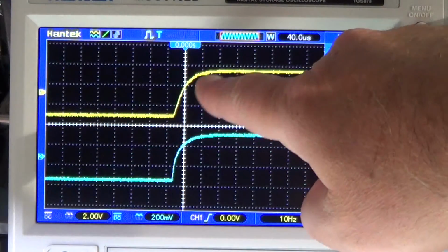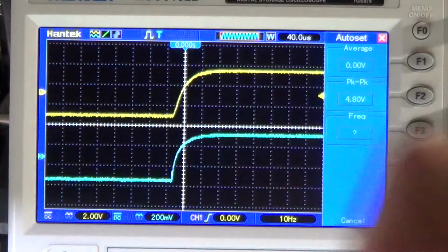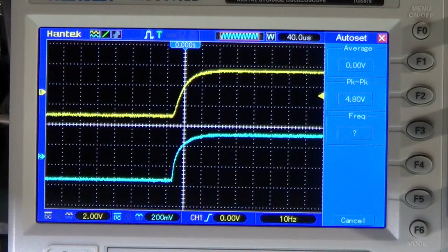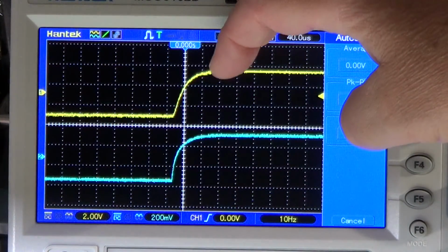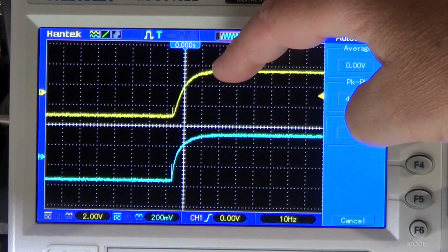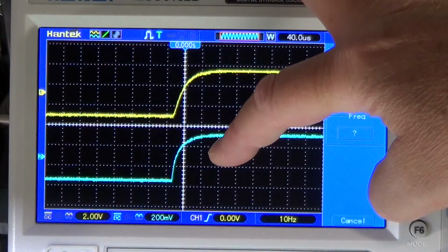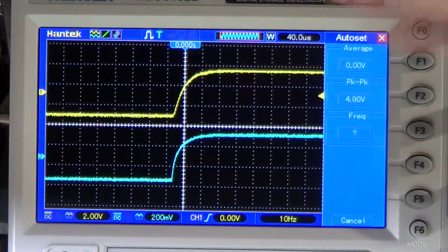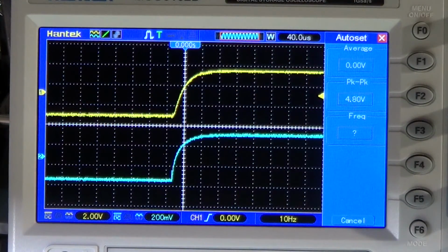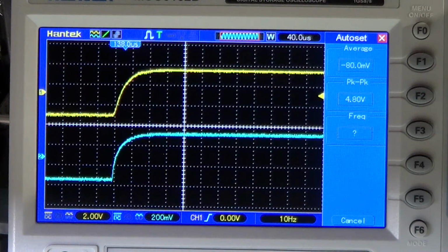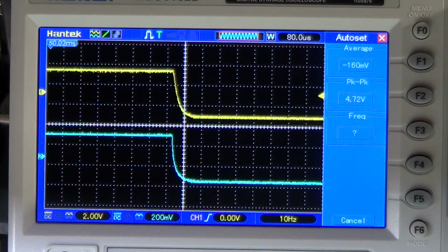You see how much smoother this line is with respect to this one. And this is because there is a greater amount of attenuation here for the various frequencies, the harmonics of the square wave, than there is over here, where the attenuation is less. Let's take a look now at the other end, basically when the signal goes down. See again.